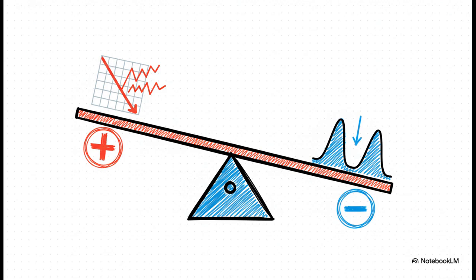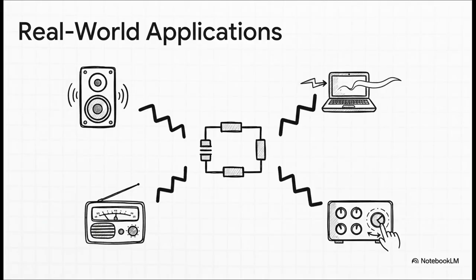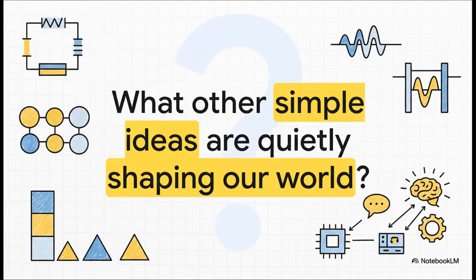It's a balancing act. So where will you find our little electronic bouncer working? Oh, just about everywhere. We're talking audio speaker systems, just like we started with, directing all that bass to the woofers. They're in the power supply for your laptop, smoothing out the electricity. They're used in radios to tune into a specific station. And they're in audio amplifiers, acting as a treble cut or hiss filter, getting rid of all that annoying high-frequency noise. So there you have it, the passive low-pass filter.